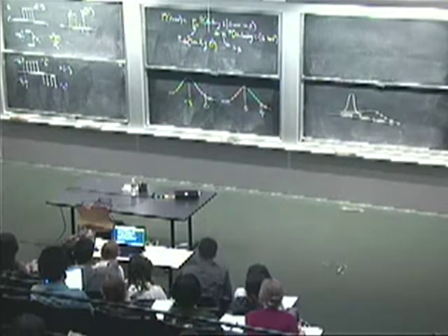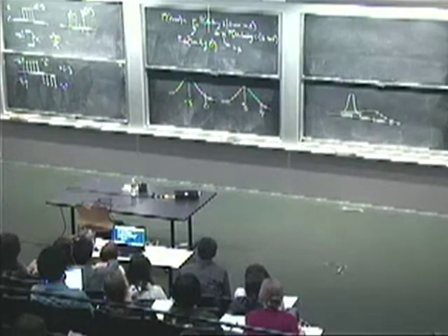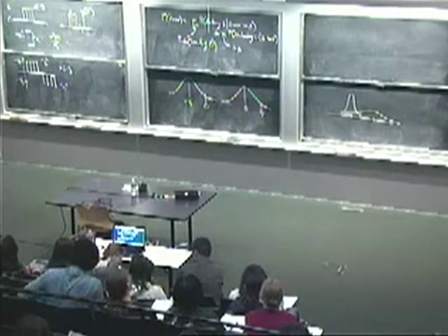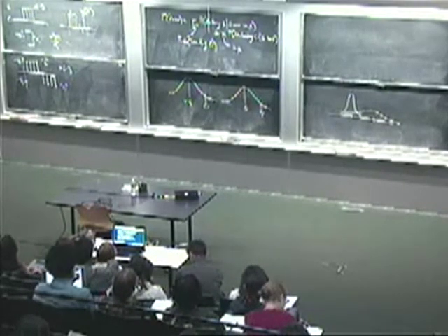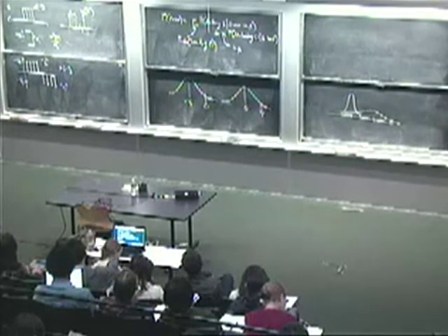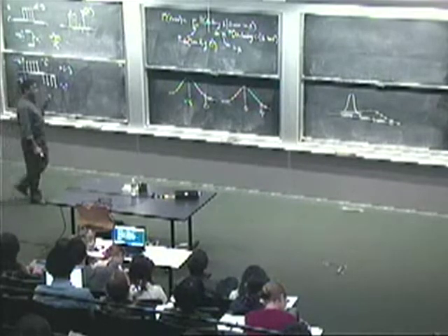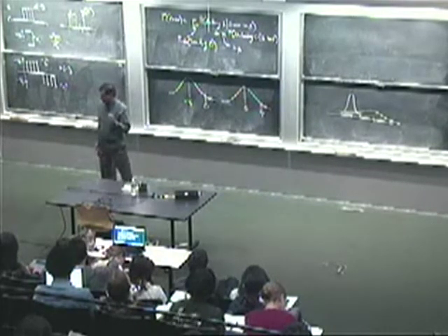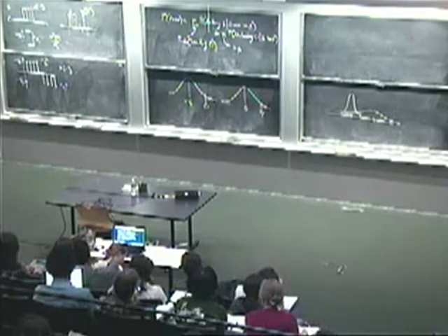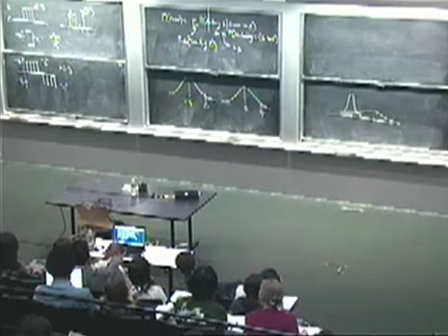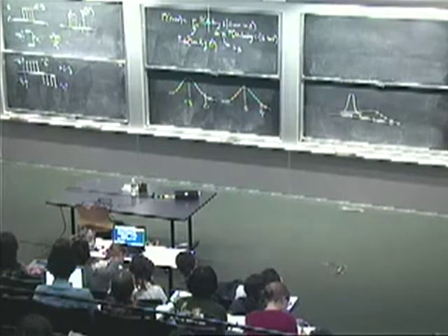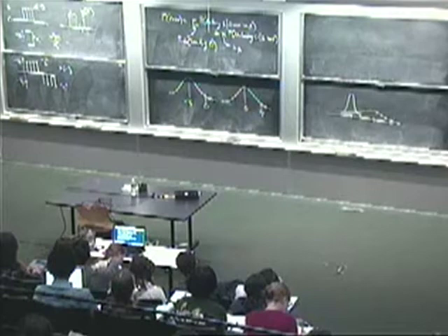So what we're saying is, here's the Gaussian. It's centered at 0, so I don't have to subtract any term off that term in the numerator. Here's the 2 sigma squared in the denominator. And I integrate it from VP onwards. There's this notation introduced. VP is square root of ES. The reason is that we're thinking in terms of the energy of a single sample or the power of a single sample. They turn out to be the same thing because it's just a single sample. So it's just a notation that's traditionally used. But what we're talking about is VP there. Okay, so the area from VP to infinity under the Gaussian with the normalization factor here.